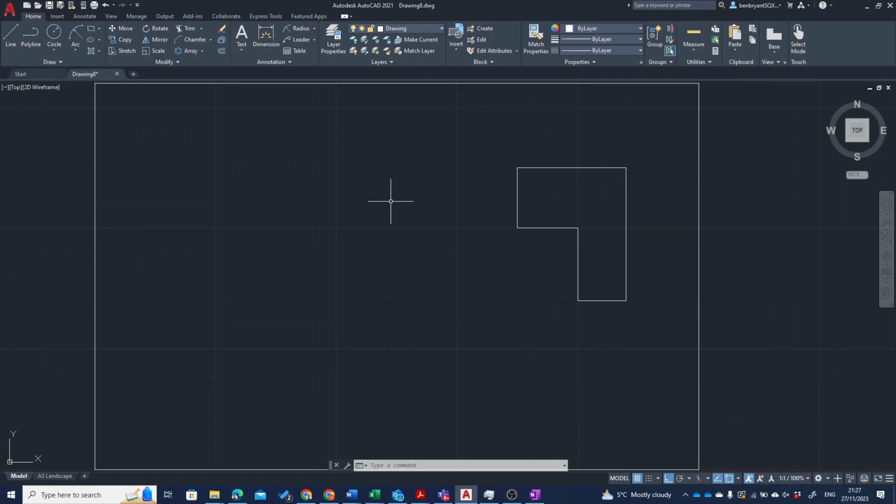So again, this is just me using the line tool this time. 15, 150, enter. And again, I've still got my axis locked in 90-degree segments. It's going to pull down 50 for the length, enter to confirm, and escape to cancel the command. So that's my first one.